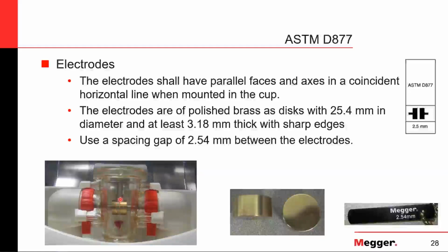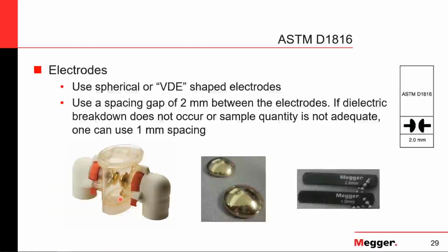That is the reason IEEE's recommended standard for transformer testing is the method described in ASTM D1816. D877 is recommended for new unprocessed oil received directly from a supplier or service-aged oil in circuit breakers.